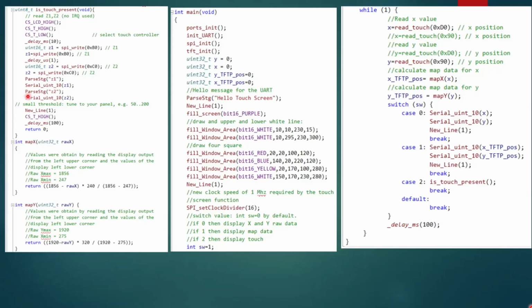Next, we can transmit that data to the serial interface, so we know what the value is. Again, I'm not using that, but if for some reason you need to know whether or not the display has been touched, then you would use those parameters, and you would have to calculate the delta of C1 minus the delta between C1 and C2, and that would tell you whether or not the display got touched. But you have to actually do it to see what numbers come out.